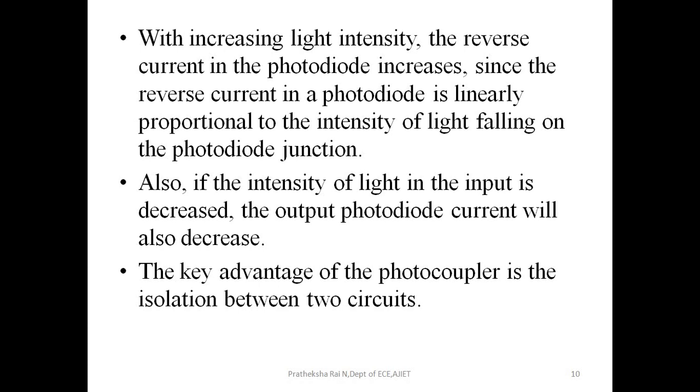They are not connected, they are isolated, but still we are getting the output as we want the specified output. We want an increase or decrease. It will just depend on how you are going to change or vary the input signal, and depending on that, the LED will give the output as light, and depending on the intensity of the LED light, we will get the output across the photodiode. So I hope the photocoupler is clear for you.